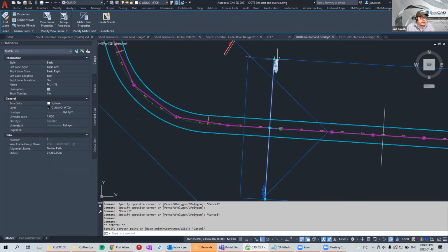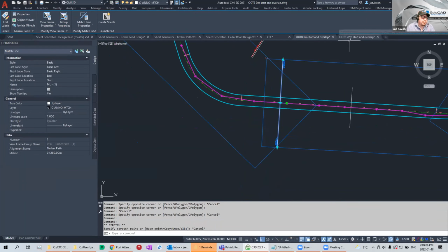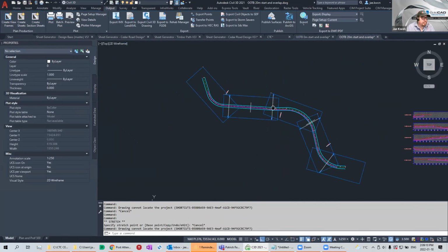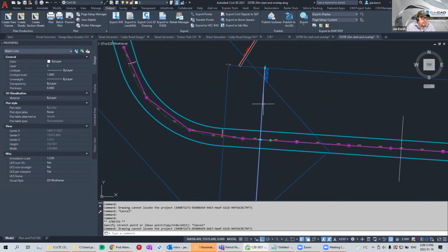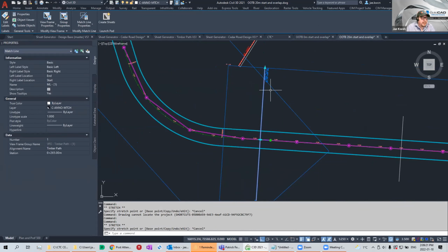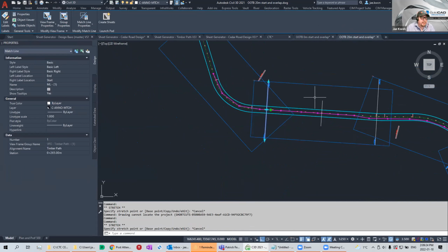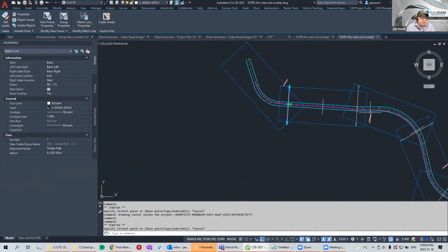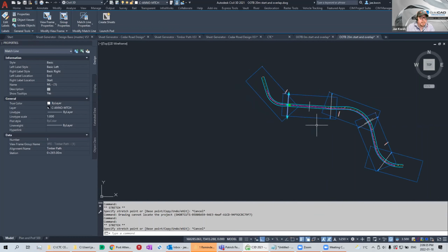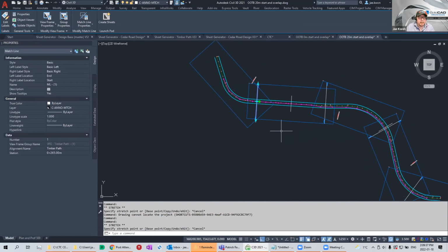That's because this was created with a 0 meter overlap. Now you can anticipate overlaps and create one with an overlap. So this one's created with a 20 meter overlap. That lets you go back a little ways, but only to a certain extent. And you can't make that number too big, because every time you bump up the overlap number, it compresses all the view shapes together. And then you end up having way more sheets than you need, possibly, right? So maybe that's not what you're looking for.